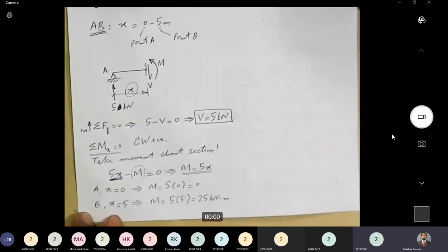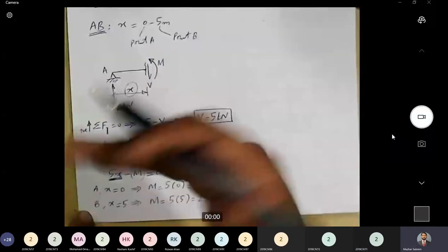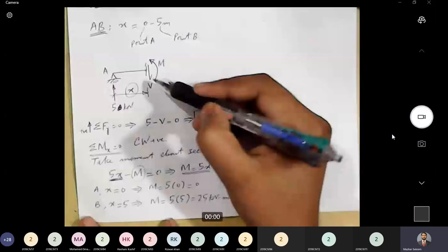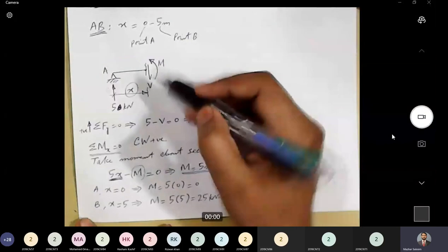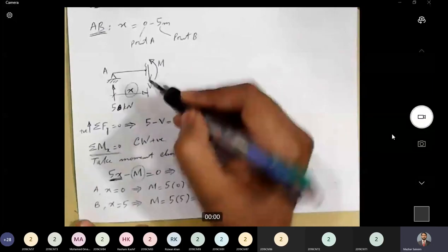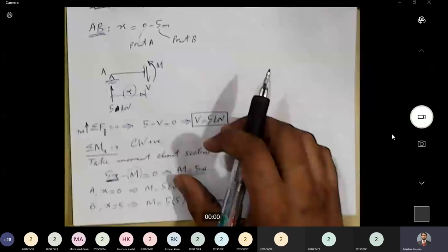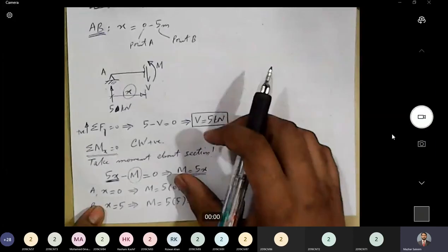Yes. The location will be this. These are the internal forces at this section. So wherever you are cutting the section, you will show these internal forces. These internal forces are not visible, physical quantities, but these forces are there. So we will always show these forces at the section. These are internal resisting forces that are creating the overall equilibrium. So we will always show these forces here.